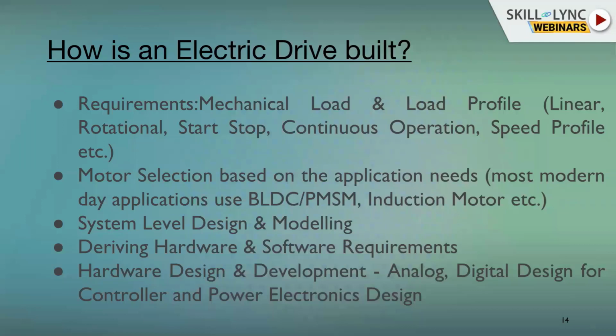The hardware requirements drive the hardware design and development. This goes into both the power processing unit, which is the power electronics part, and the controller, which involves analog and digital design. The hardware design output would be PCBs, and for power electronics, it could be PCB mounted, or parts directly mounted inside a mechanical chassis.